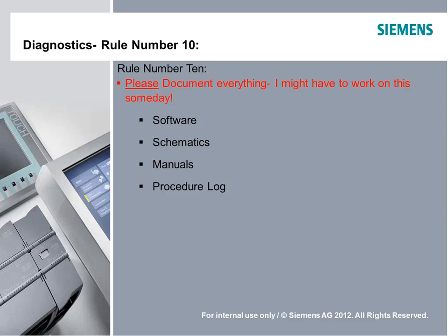Remember that it's not always the most complicated part, and that kind of goes along the lines of localizing the problem. Typically even within a subsystem, people tend to think, it's that crazy PLC thing. It's not the sensor. Especially if things are acting crazy, with intermittent problems or just a networking issue or loose wiring, sometimes it's a ghost in the machine. Boy, that just doesn't make any sense at all. But if you localize it, look at just the small picture of what's happening there and are able to reproduce the problem, you should be able to get that fixed.